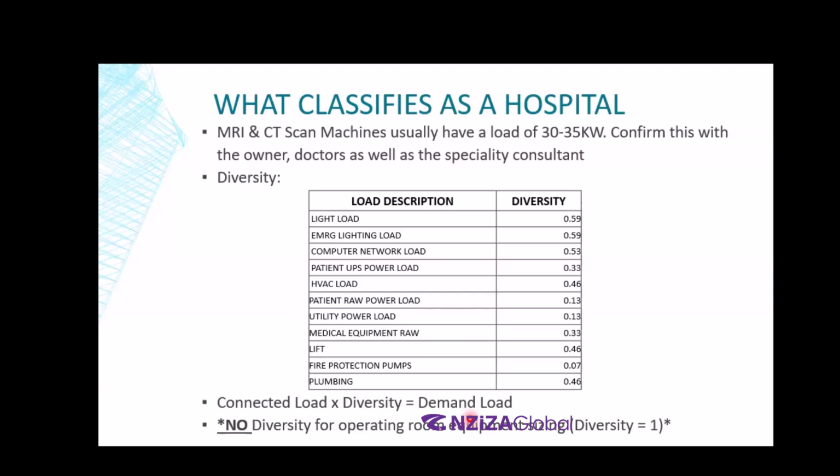So the load, basically you're talking about when we will be sizing the transformer for the entire facility, you will take into consideration the demand load, not the connected load. Is that concept clear now? Okay. So now talking about the operating room. As I mentioned, operating rooms are very critical. Rest of the areas you can apply a diversity factor, but no diversity factor for the operating room equipment sizing. You need to have it at 100%.